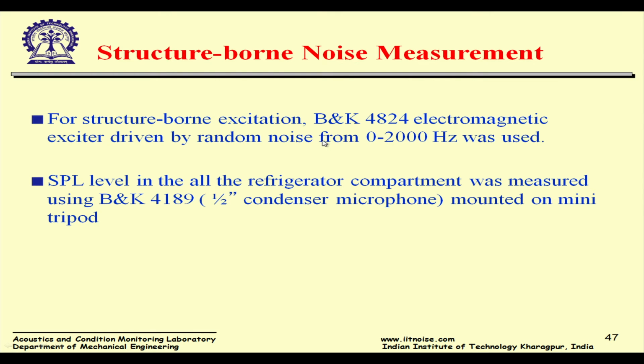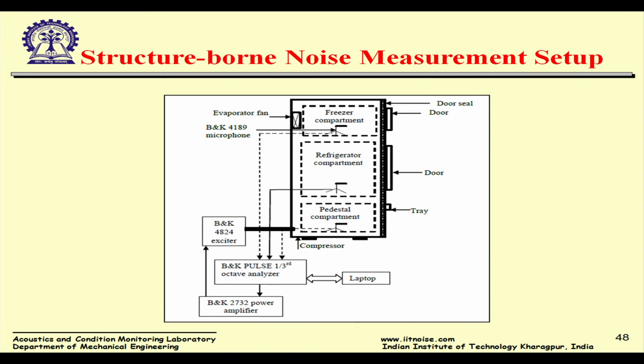And for the structure-borne noise measurement, what we did, we removed the compressor, and at the mount location we excited it mechanically, and then we found the transfer function between the structural location at the mounts and the SPL in the interior of the refrigerator, and we plotted that.